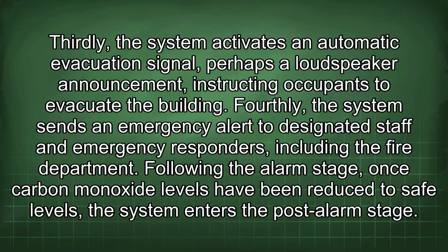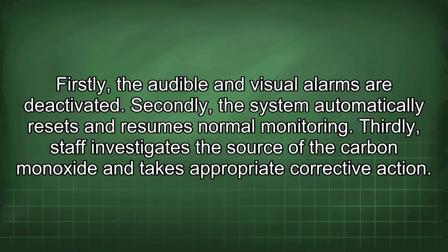Following the alarm stage, once carbon monoxide levels have been reduced to safe levels, the system enters the post-alarm stage. Firstly, the audible and visual alarms are deactivated. Secondly, the system automatically resets and resumes normal monitoring. Thirdly, staff investigates the source of the carbon monoxide and takes appropriate corrective action.